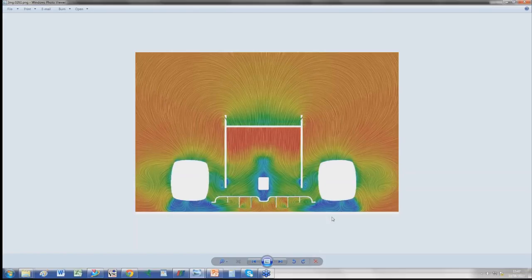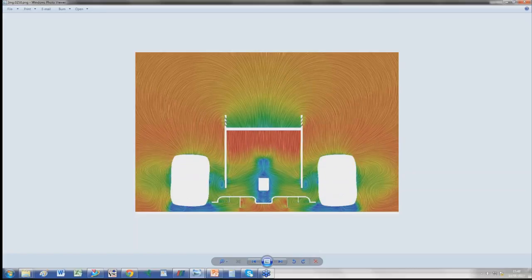Quickly, you can see what we call the louvers here, the openings on the side of the end plate on top of the rear wing. Everybody's got that. It's a small feature on the car that helps to reduce the drag of the car. It detunes the rear wing efficiently, so it reduces the pressure on top of the rear wing. And it works as well in conjunction with this vortex on the side here.